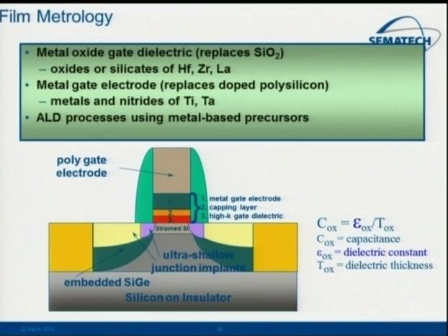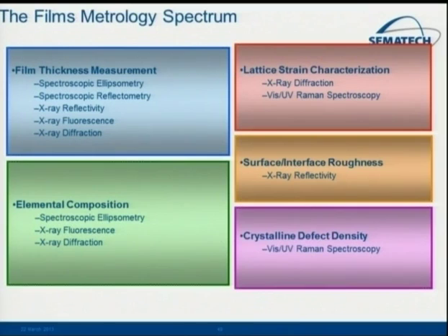So like metal oxides, you may not just have hafnium oxide. There may be other things in the stack. The atomic layer deposition processes usually use a complex type of precursor, with different materials in there. How do you make sure you're putting down a film that has the right physical dimensions and electrical properties that you need? To do that, there are a lot of techniques.